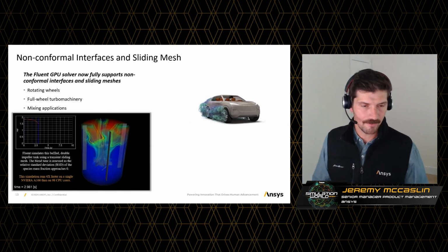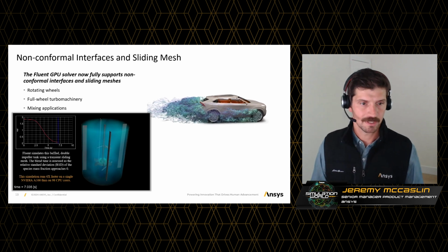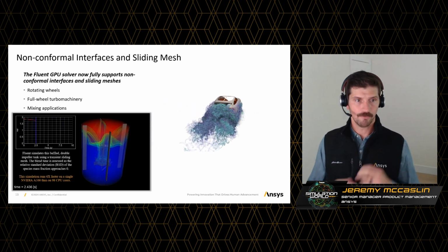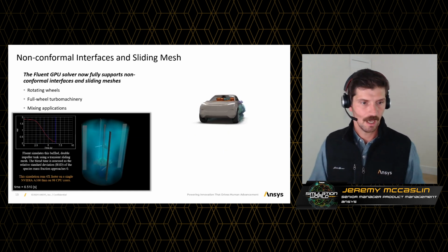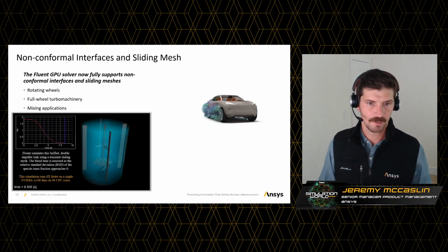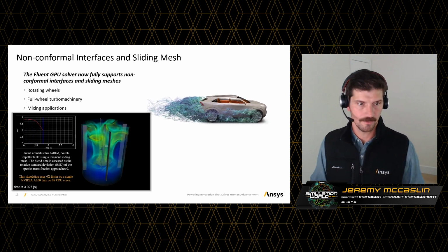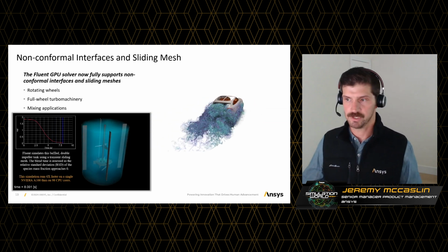We have support for non-conformal interfaces and sliding mesh. This allows you to do simulations that have rotating wheels, full wheel turbomachinery, and lots of different mixing applications like you see in the case on the bottom left. And for external aerodynamics, if you're looking at cars, the rotating wheels are an important aspect that we can now cover with the GPU solver.